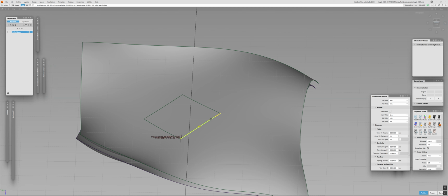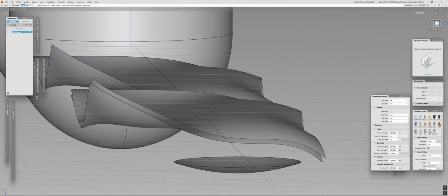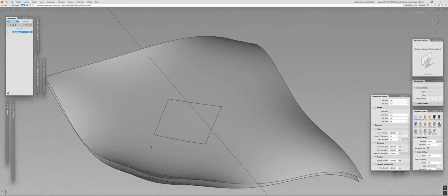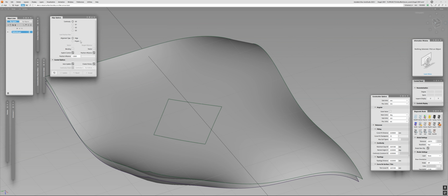Once again, it works with the automatic and we have these issues here, right? But even though we already sacrificed to some extent our equidistance between the two, in return, we get pretty clean surfaces. So what that means is I can retrim this surface, just delete these curves, and guess what? I can just reproject.